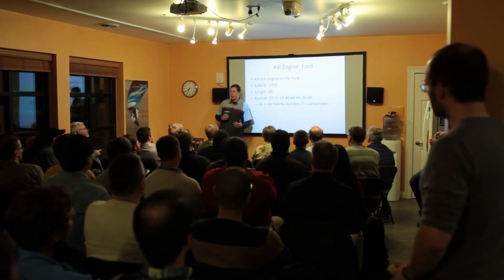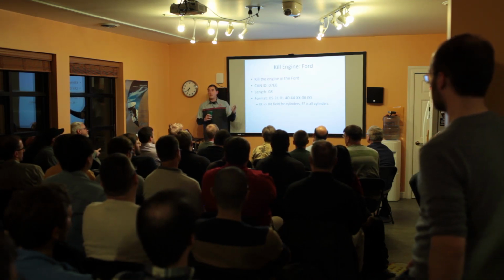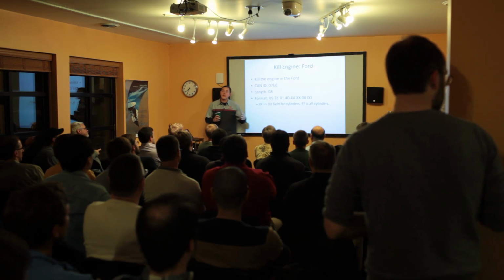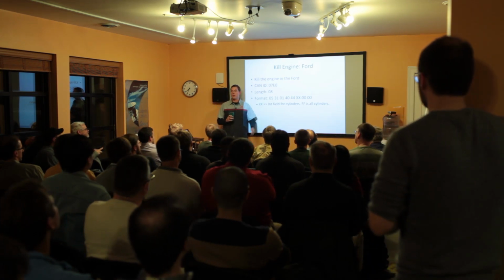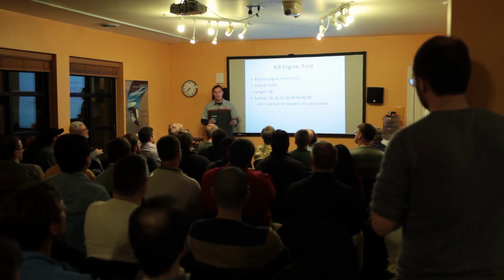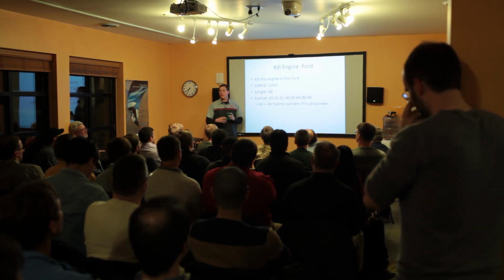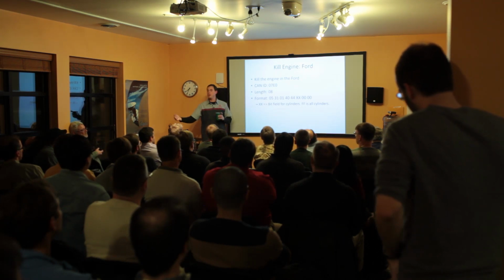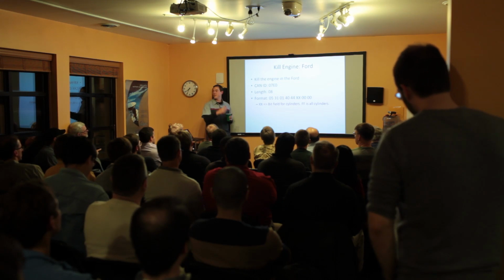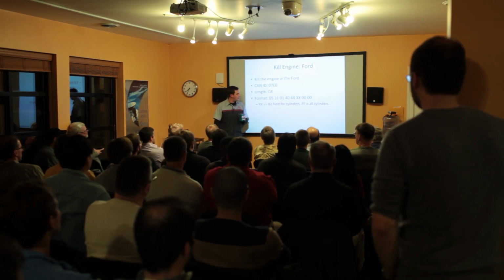What can we do with these diagnostic messages? For a lot of them, we honestly didn't need security access. They just kind of worked as long as we figured out what they were. How do we figure out what they were? The mechanics software has these tests in them, so the mechanics can do them, right? So we just set up our sniffer, run the test, see what bytes happened, and there you go.